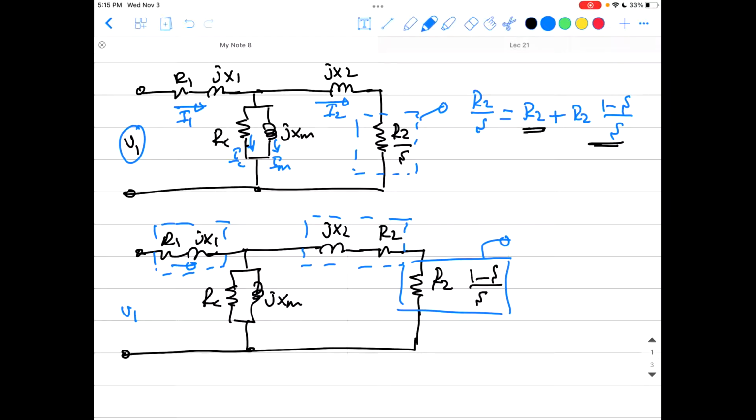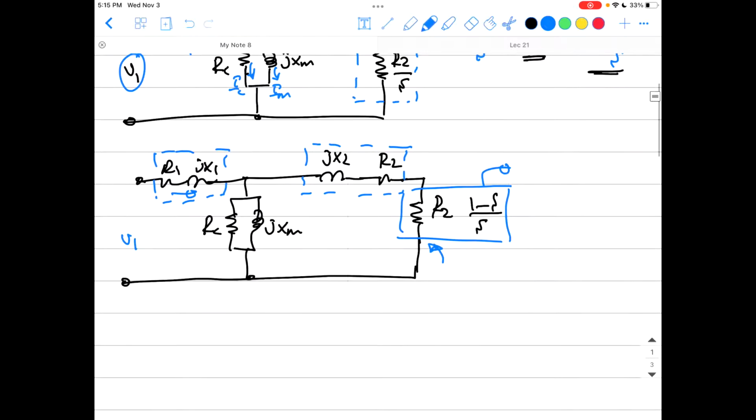If you look back to the equivalent circuit of a transformer in your previous courses, it will look exactly like this circuit, except that in place of this resistance, you will have the load attached to the secondary of a transformer. We'll do the same here. So this looks like the load on a transformer, but it's dependent. We call this the dynamic load. Why? Because it depends on the slip.